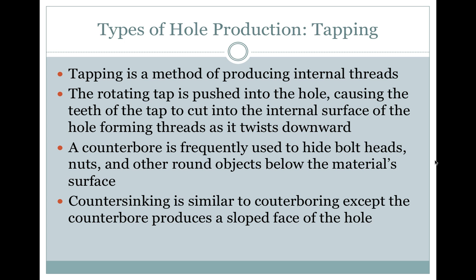Tapping. Tapping is a method of producing internal threads. The rotating tap is pushed into the hole, causing the teeth of the tap to cut into the internal surface of the hole, forming threads as it twists downward.